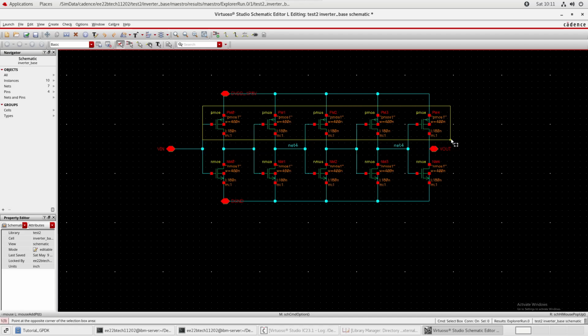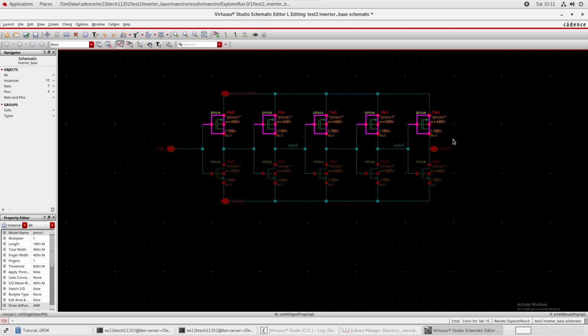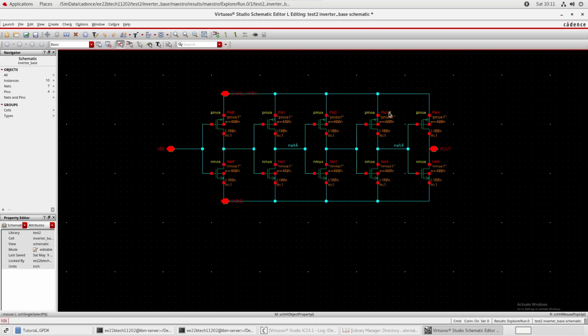If you have some huge design and you are bringing in some block, some op amp or something, it's best to give it some name specific to it, so that in simulation it can be very easy to find out where the issue is, because when you see issues it will tell you that the issue is with PM3 in the hierarchy, and it will tell you the entire hierarchy.